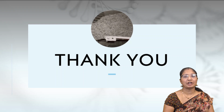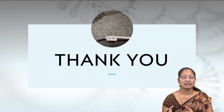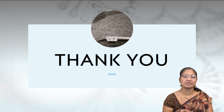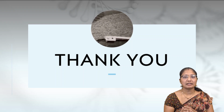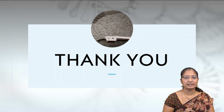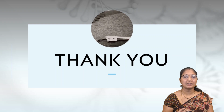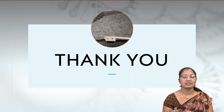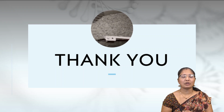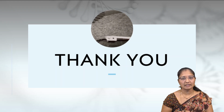This happens from 1 to 28 days and continues for almost 1 year. This continuous process gives the rigid and hard strength to the cement. The crystallization of the calcium hydroxide and the gel, and the hydrated tricalcium aluminate formation, give strength to the cement, which increases the hardening process. This is about the setting and hardening of the cement and the reactions involved in the hardening process of the cement.